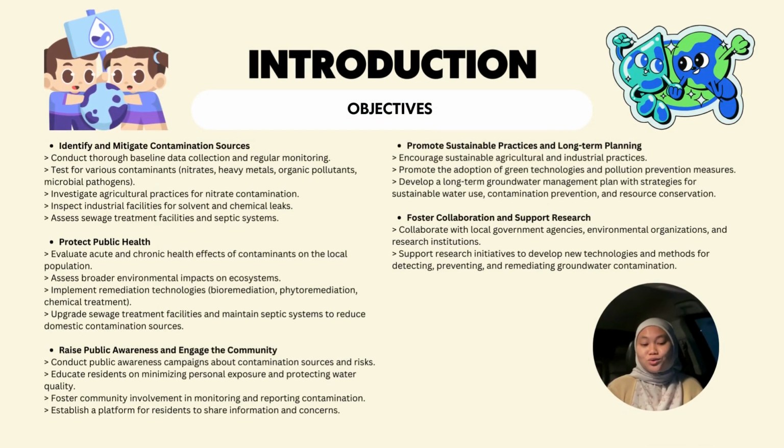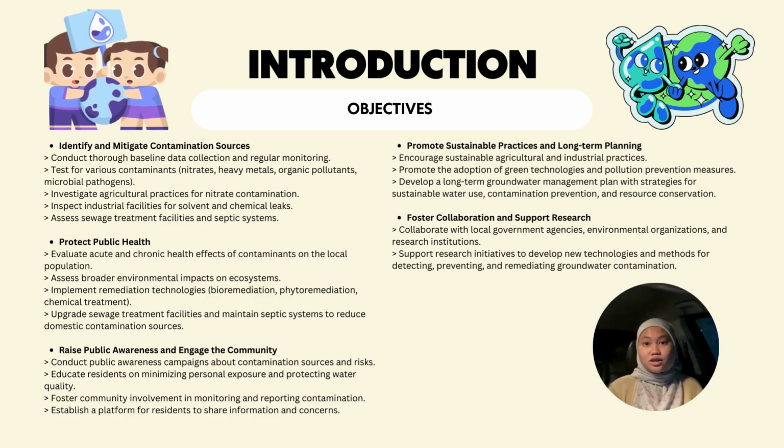Next, we jump into the objective. The first one is identify and mitigate contamination sources. This is about conducting thorough baseline data collection and regular monitoring, testing for various contaminants, investigating agricultural practices for nitrate contamination, inspecting industrial facilities for solvent and chemical leaks, and assessing sewage treatment facilities and septic systems.